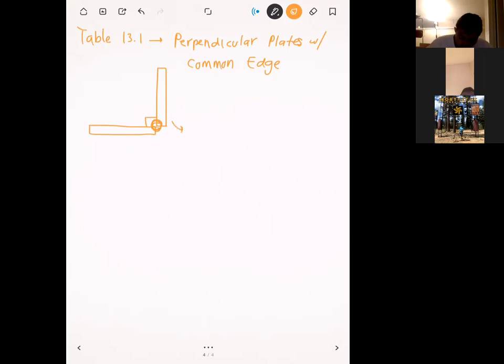If you look in that table, you can see the formula for the shape factor F12. Let me write it down here, with a bit more space. F12 is equal to 1 plus L2 divided by L1, minus the quantity 1 plus L2 divided by L1 squared, to the 1/2 power.